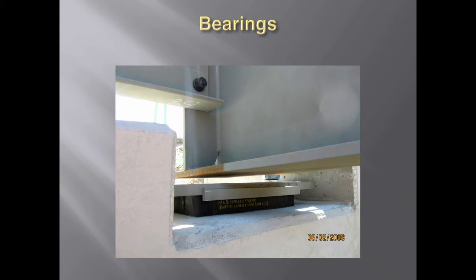This one happened to be that the center bearing, there was a bent, and they put the wrong ones in it. And when they set the bridge on top of it, because the wrong bearing was set in there, it's too thick, you basically end up with a floating girder. As you can see, there's a space in there. That's not supposed to be there.